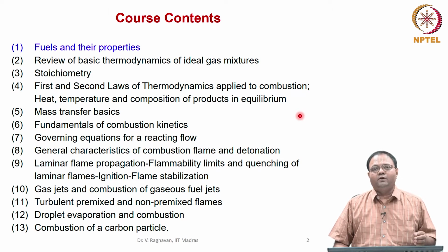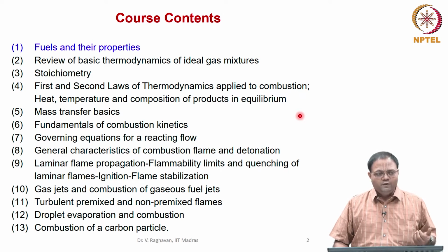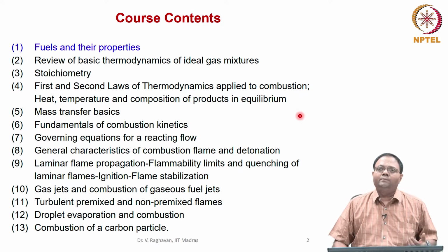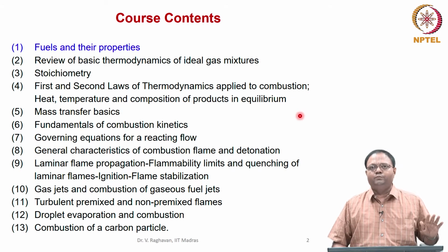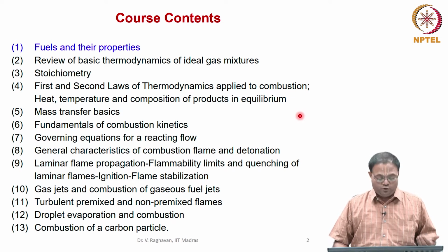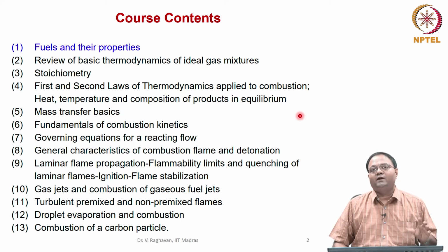So this basically comes after we decide what is the rate at which fuel is fed into a combustion chamber. So once we know that, then along with the fuel, how much oxidizer. So normally if you say air is the oxidizer which is available in atmosphere, it has oxygen, and this oxidizer has to be supplied. So when you want a combustion to take place, we need two species basically. One is called fuel species, another one is called oxidizer species, and how much amount of fuel is decided by the power rating of the combustor.